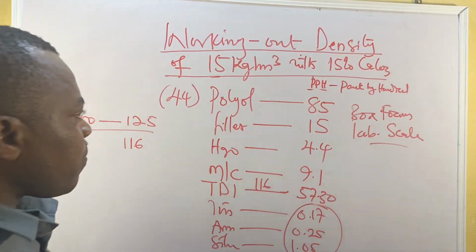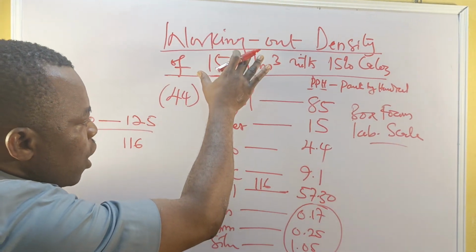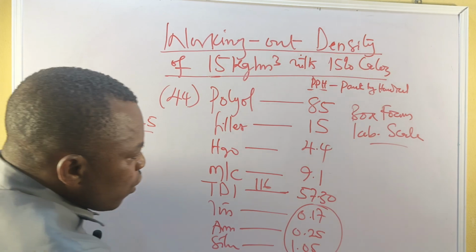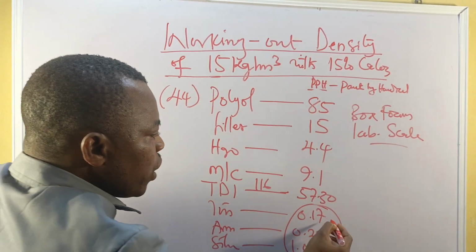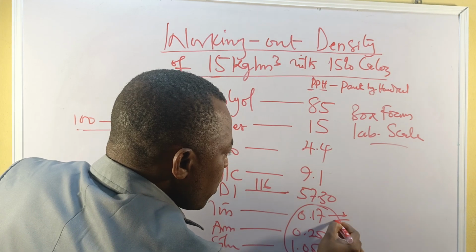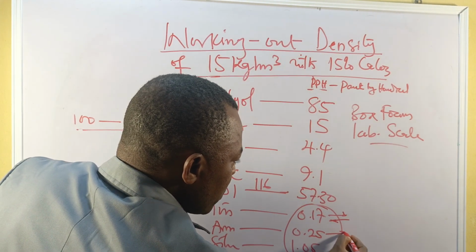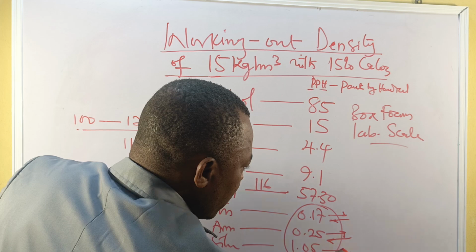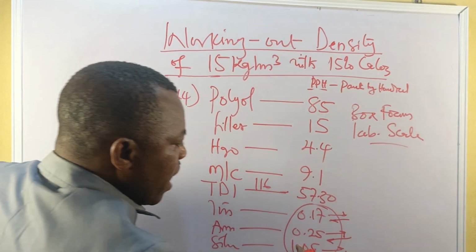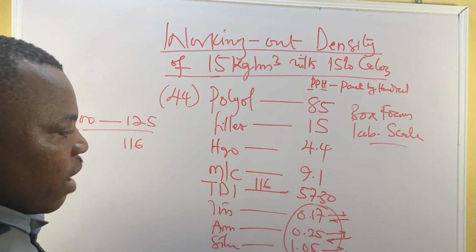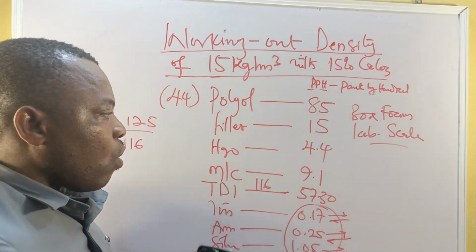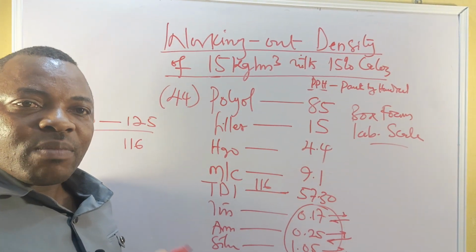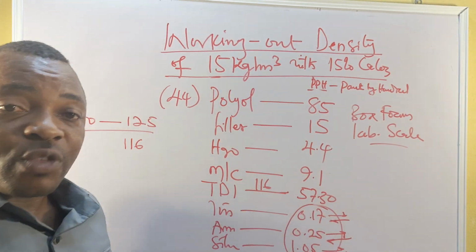In the laboratory scale, it will enable you to check when you need to reduce this, increase this, or reduce this, because silicon there is a stabilizer. When the foam rises at a full rise, the figure will be generated, so the foam will not tend to make any mistake of collapsing because of the presence of silicon.